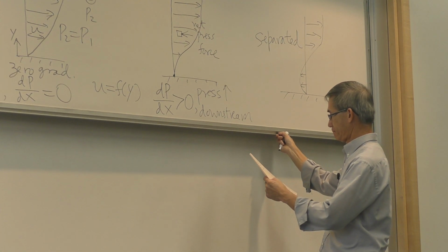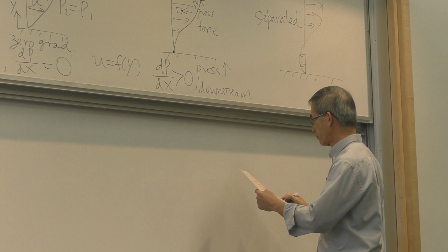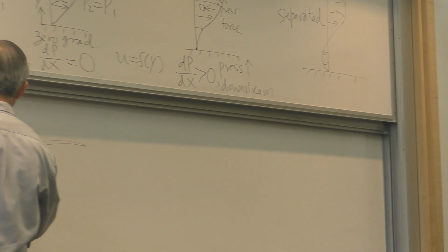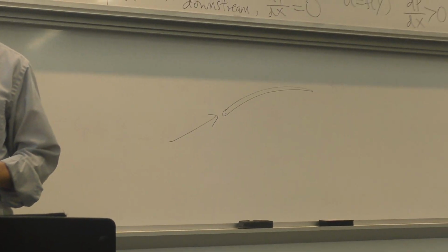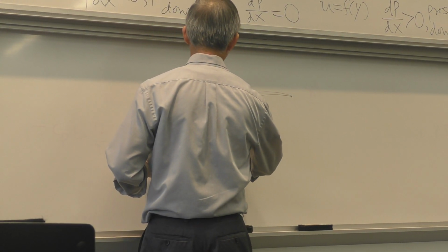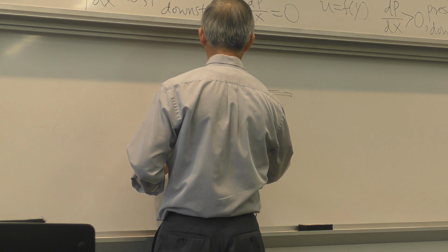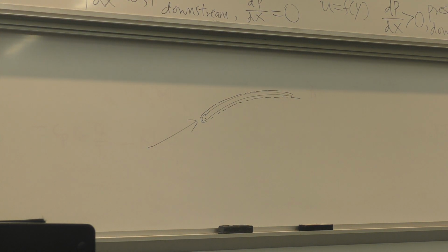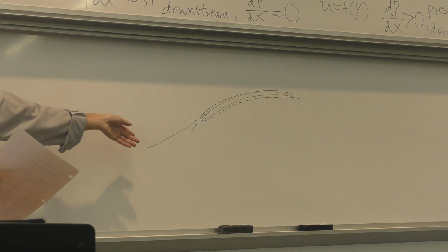And to illustrate that, if I have an airfoil that's very well oriented to the flow direction, meaning the airplane is cruising nicely and steadily, the flow and the pressure gradient around the upper and lower surface is such that the boundary layer is attached. It's very well behaved. And my design of the airfoil shape, by intent, allows this boundary layer to remain attached under cruise condition at relatively small angle of attack.